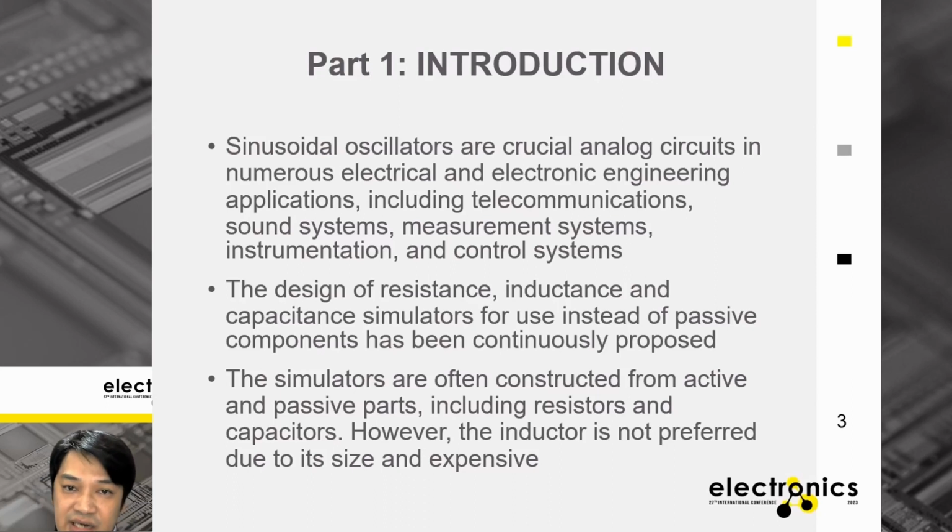The sinusoidal oscillators are crucial analog circuits in numerous electrical and engineering applications, including telecommunication, sound systems, measurement systems, instrumentation systems, and control systems. The design of resistance, inductance, and capacitance simulators for use instead of passive components has been continually proposed. The simulators are often constructed from active and passive parts, including the resistor and the capacitor. However, the inductor is not preferred due to its size and expense.